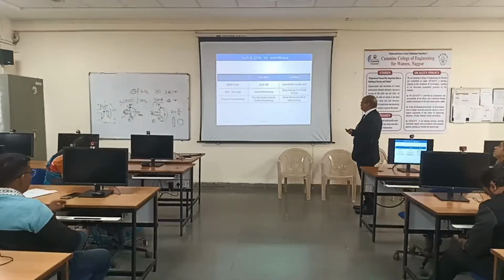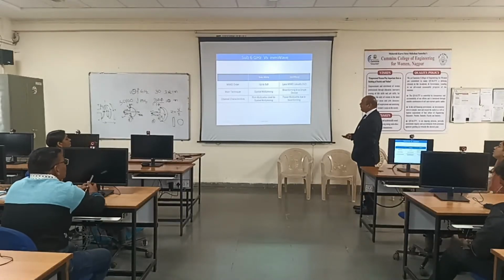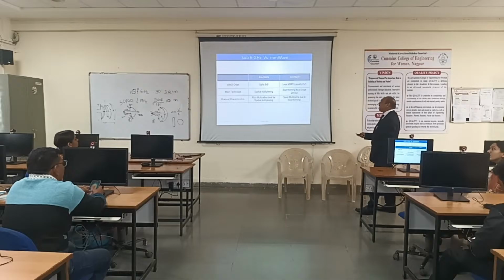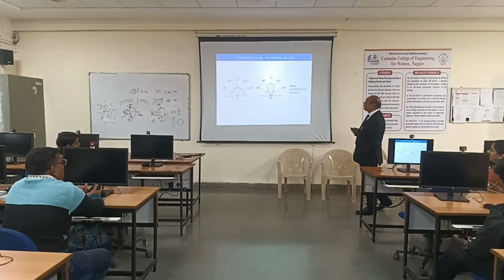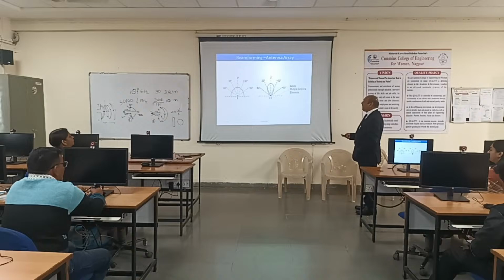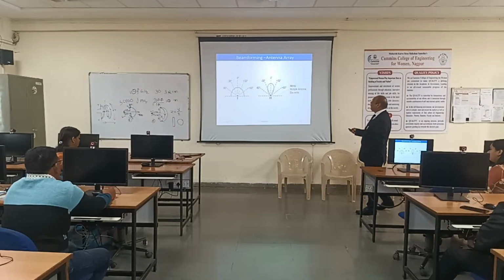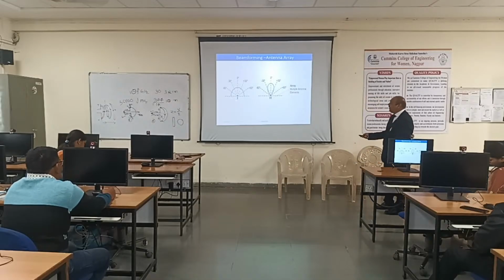This is beam forming to a single device. Then this is a single user. This is multiple user. Simple. Okay. Then channel characteristics: rich multi-path, ideal for the spatial multiplexing, pure multipath due to the beam. Okay. Next. See, this is the single antenna which radiates equally in all the directions, 360 degree. This is the radiation pattern. If you use the multiple antenna elements, if you use one array, तो gain will increase. Okay, you can get it with this diagram.